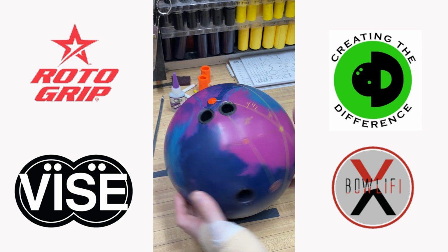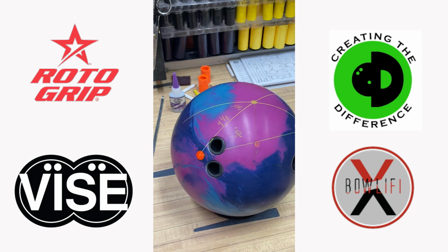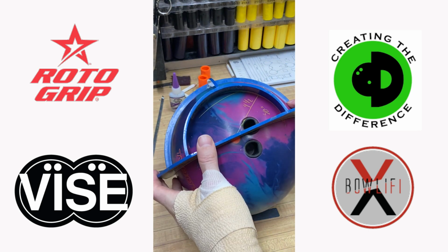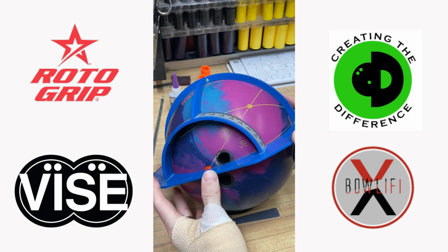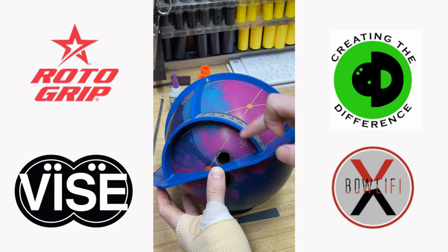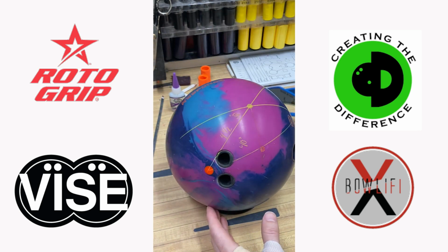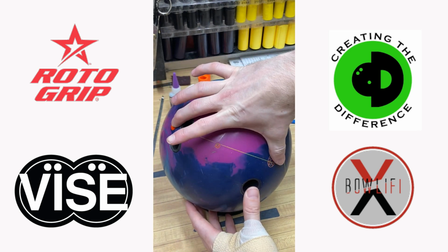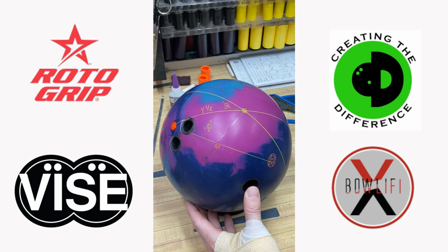The next step is I'm going to figure out what I want my first angle in the dual angle layout system to be. So I have my PAP here, and you'll see I lined it up on that line, and this angle is a 40-degree angle. That's what the first number means, the angle between the pin to positive spin axis line and the pin to PAP line.